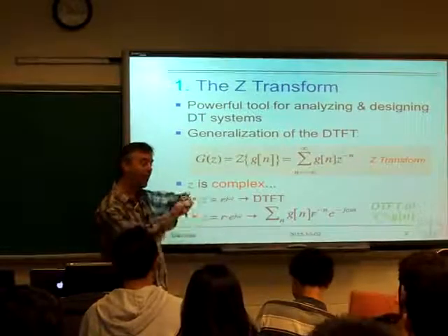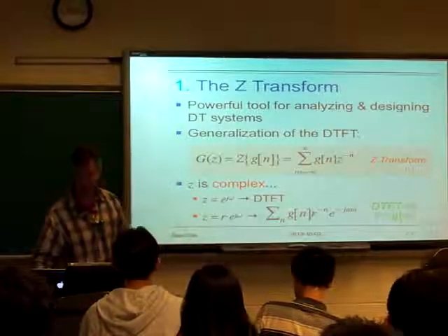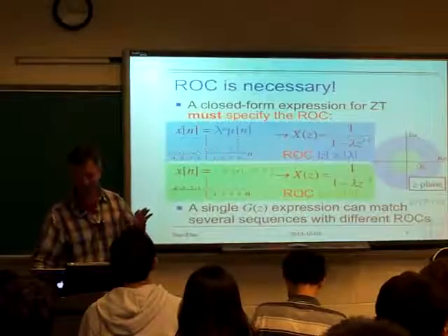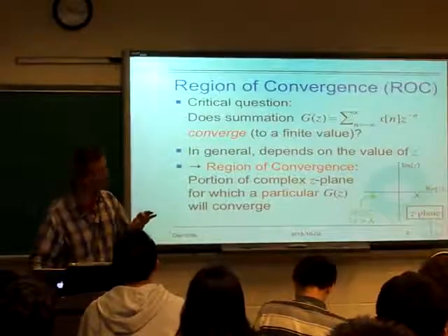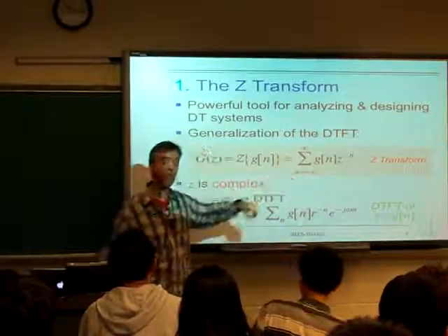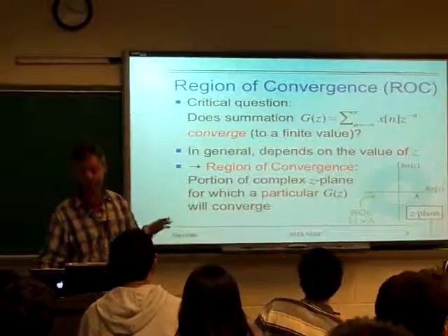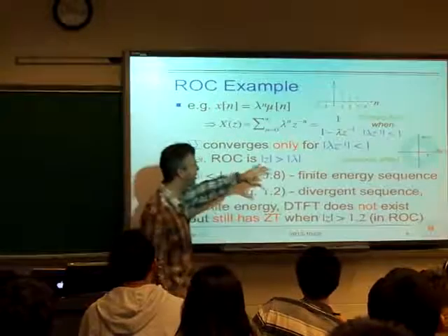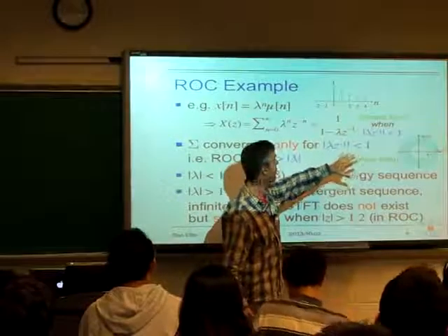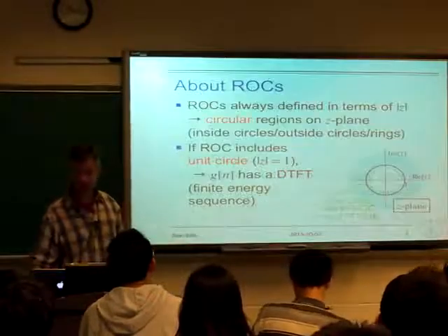We can get the Fourier transform from the Z transform just by looking at the particular values. And then region of convergence, okay. If we define the Z transform like this, for certain forms of sequences, we can find a closed form expression for the Z transform, which has a limited region of convergence. But assuming that we're interested in the values in the region where we do have convergence, then we can have these nice closed form expressions which can give us the value anywhere on the surface.